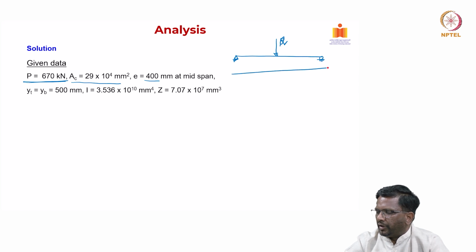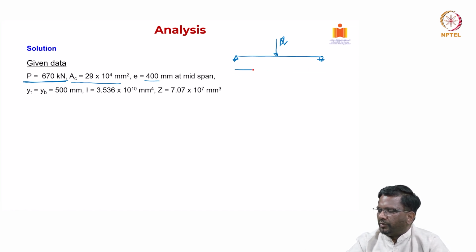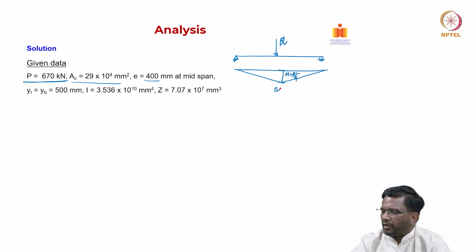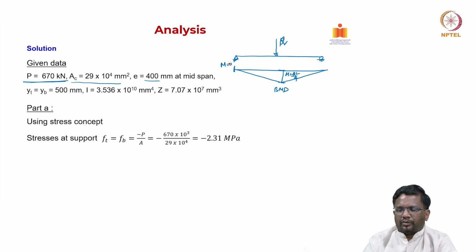So you will know that it is also subjected to some self weight, right? For the applied load, we know that this is QL by 4, this is your bending moment diagram, right. At this location, moment equal to 0 at support, right. So the only force that is acting will be the pre-stressing force.